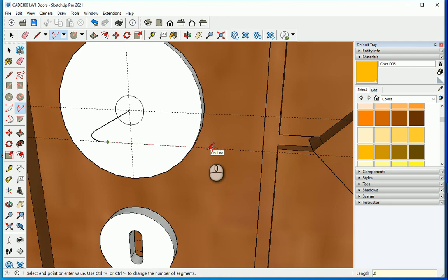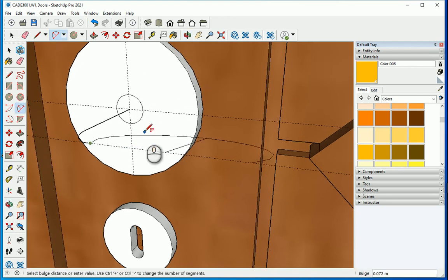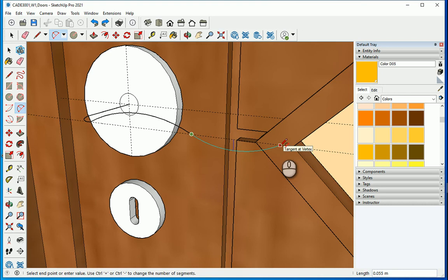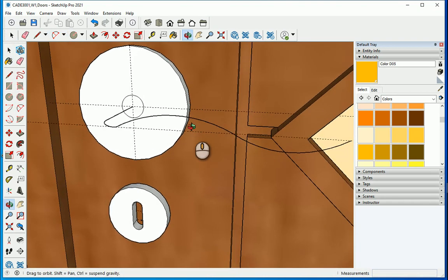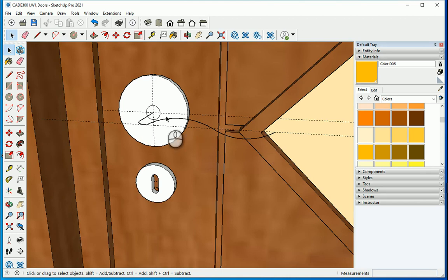Maybe I'll go with 0.08, 8 centimeters, and if you hit the top arrow key, it moves in this direction, actually the Z direction. So maybe I want to have a little bit of a curve around here. So this is good. I can assign a number, let's say 0.01. I want to go with 0.07 maybe. And I want to move this down. You can hit the down arrow key, and maybe this is 0.01. So this time the handle is a little bit more flexible, more curved.